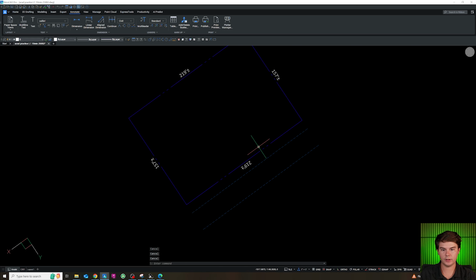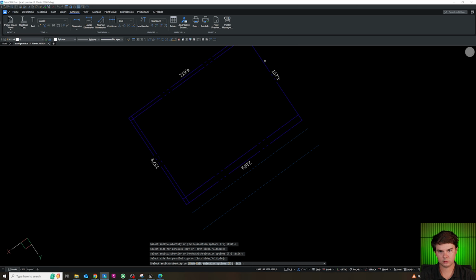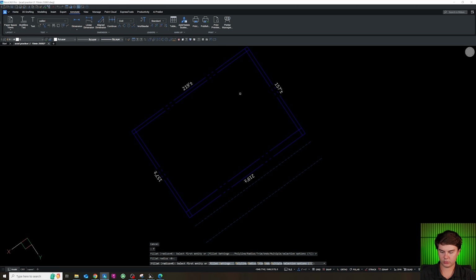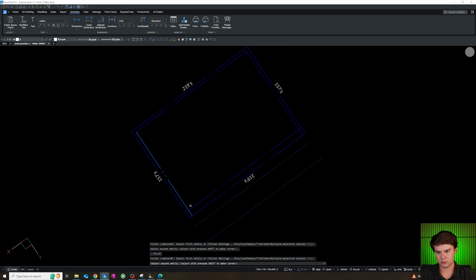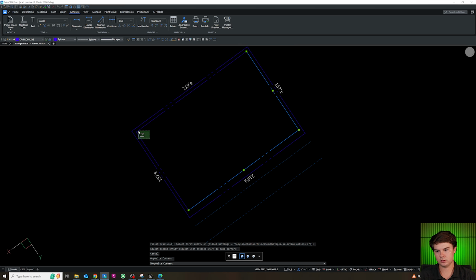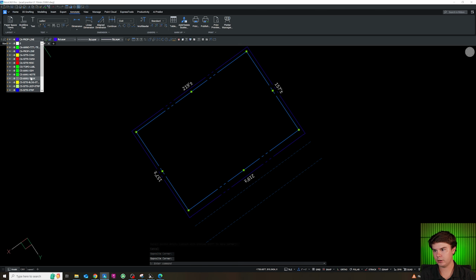Now I'll put in our landscape strip, which is 10 feet in the front. So you offset the property line 10 feet and then 5 feet everywhere else. And then we'll connect these with FR0 just to fill it with a radius of 0. Just auto trims it for us, which is very nice. Put these on the landscape strip layer.